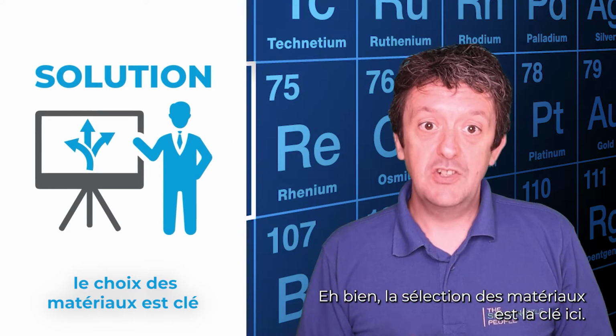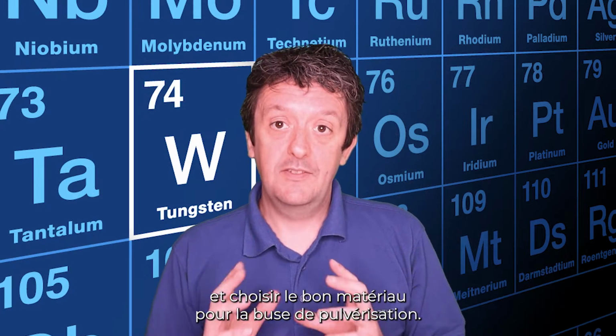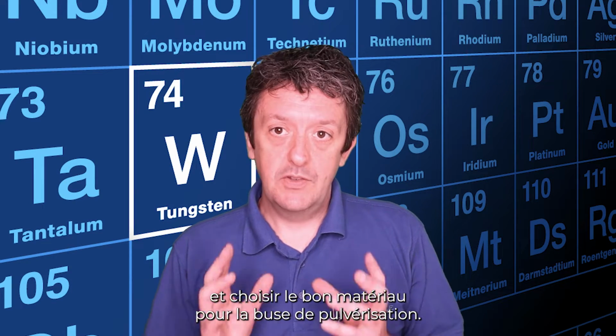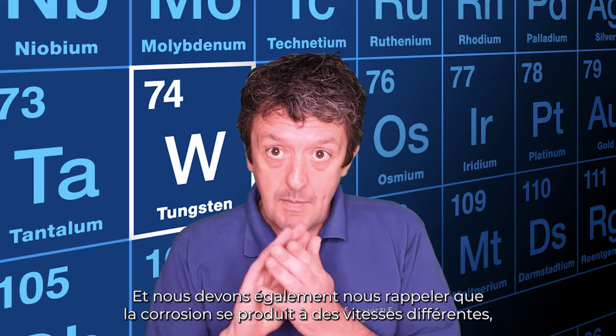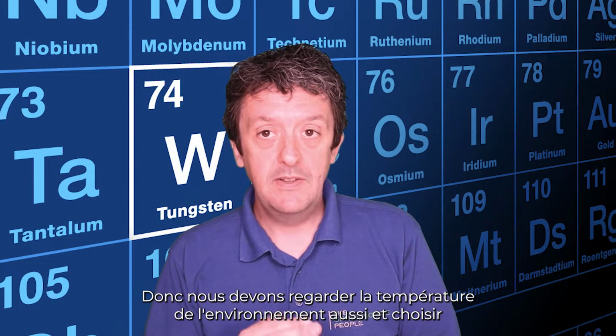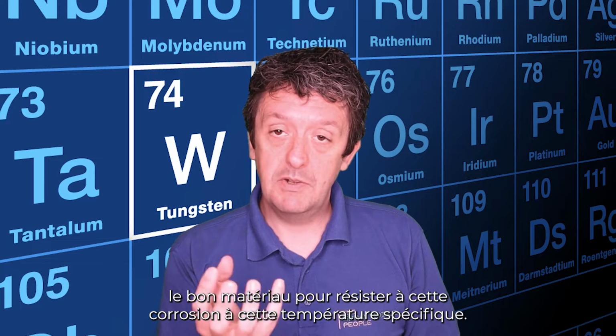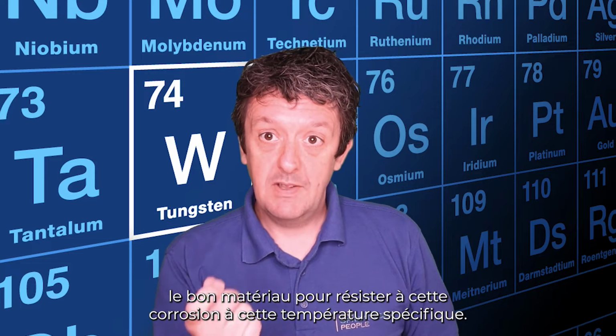Well, material selection is key here. We need to look at the environment, look at the corrosives in there, and select the correct material for the spray nozzle. And we also need to remember that corrosion occurs at different rates at different temperatures. So we need to look at the temperature of the environment as well and select the correct material that will resist that corrosion at that specific temperature.